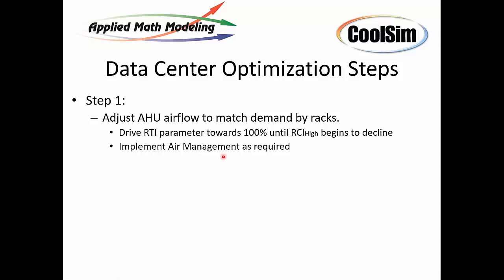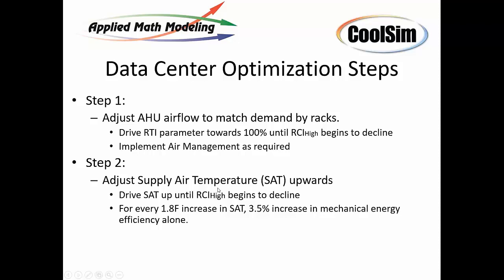And implement air management as necessary. This tells you a lot by itself. Just taking the total amount of air that's going into the room and starting to decline it will show you where the room has trouble, where the environment is struggling to get air to where it needs to go. It's always the case. So this exercise alone tells you an awful lot about what you need to do in the data center to make it healthy. And then once you've done that, you have the opportunity to drive up supply air temp.